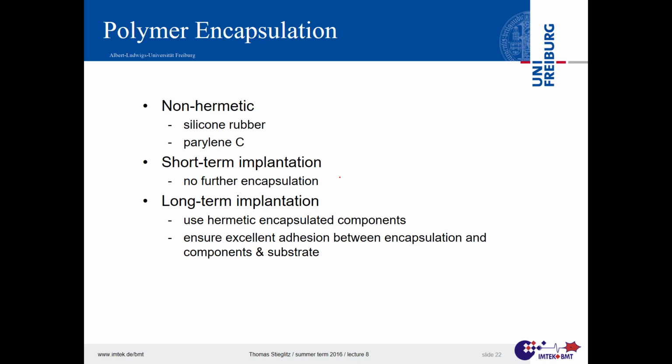And I was really astonished. Two of my PhD students wrote a report on something. I said, well, we cannot hand that report in, it sounds a bit stupid. You did something and the silicone rubber remains sticky. That's well known. If you take the wrong gloves with certain silicone rubbers, you have sulfur in there, and sulfur prevents proper vulcanization of silicone rubber. They said, well, we have talked to some other groups, they did not believe us. Okay, so keep it in the report.